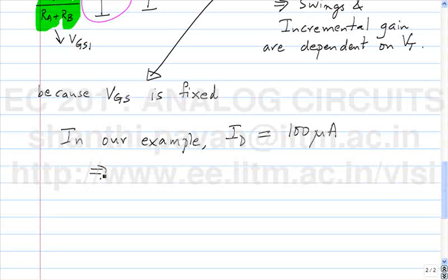You understand? So far you have been doing the forward thing, which is you apply a VGS and take whatever ID you get. Okay, I mean, it's not as dumb as that, but you have used the formula. Okay, you have used VGS is whatever, some 0.7 volts, Vt is 0.5 and all this, and found ID. What we need to really be doing is to be asking this question and answering it, which is, if I want 100 microamperes of current to flow through the drain of the transistor, what gate source voltage must I apply? So how will you find the answer to this question?